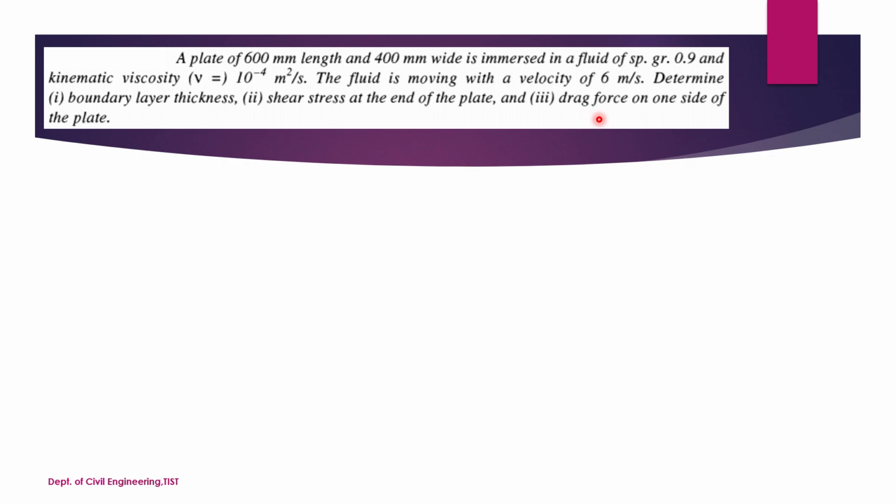If you apply the equation, you'll be getting the drag force on one side of the plate only. If in any question the total drag force is asked, then you have to multiply FD into 2. Then only you will be getting the total drag force on the plate. We have discussed this in the previous video.